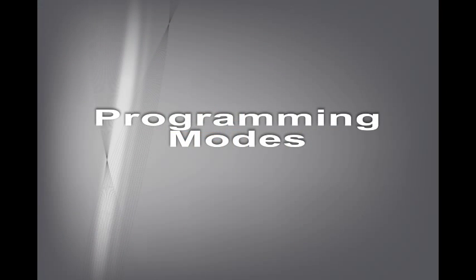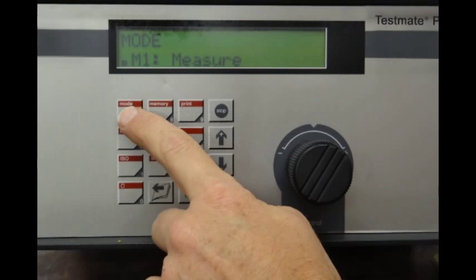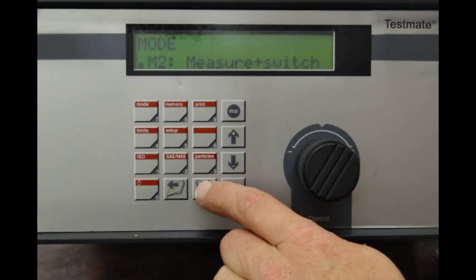As we said, the TPM is extremely versatile and has several different modes. Mode 1 is used for measuring oil cleanliness without using the control functions. This is good for short-term measurement of system cleanliness. Mode 2 is measuring and switching. This allows the TPM to signal external devices to switch on or off, for instance, an alarm indicator lamp on a control panel.